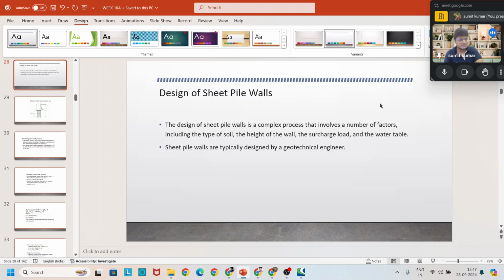But in general, the steel sheet pile walls are mostly used because they are easy to assemble, easy to install, and suitable for temporary structures. And in general, when you go across, for permanent structures you see either steel sheet pile walls or, more often, concrete sheet pile walls used to support whatever we want to support, maybe water or soil. So aluminum is also one of the things which could be used. Over there we have taken it on the basis of material, and we have stated that this is also one of the things which one can employ, when we talk about what type of sequence we could have on the basis of material, right?